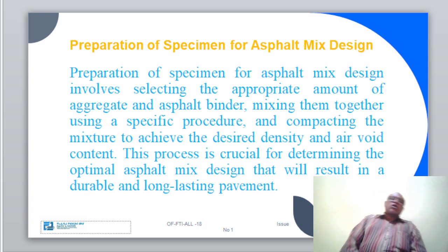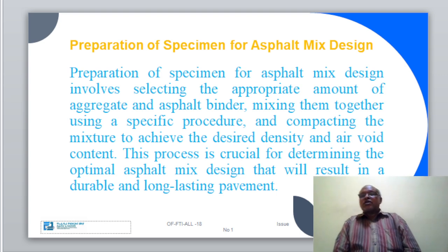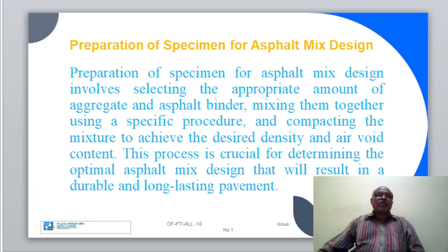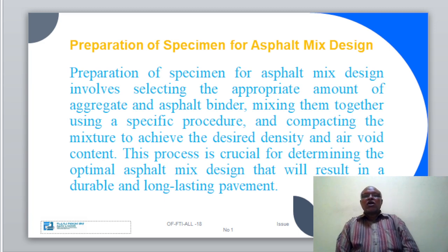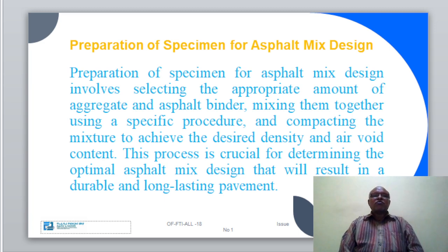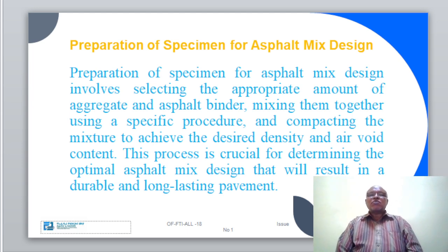Procedures for preparing specimen for asphalt mix design. First, select the aggregate components according to the mix design specifications, ensuring that they meet the gradation requirement. Second, heat the asphalt binder to the specified temperature in a heated container to ensure proper mixing and adhesion with the aggregate.